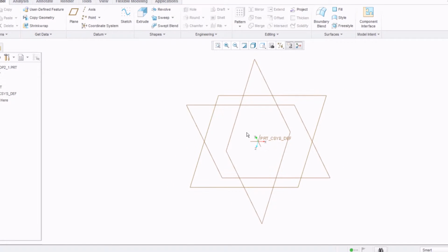So now we have a brand new reference frame here. So looking at that part, the way I want to tackle this is we're going to go ahead and create that base portion first, and then we'll come in and create the circular portion on top. So if I look at this, there's two ways to do it. I can create the shape using that bottom sketch there and just have the whole thing extrude at once. Or I can do it in two parts, one extrude, one extrude cut. I'll go ahead and use the second just to give you some more practice. So we're going to make the box first, and then we're going to extrude out the edge we don't need.